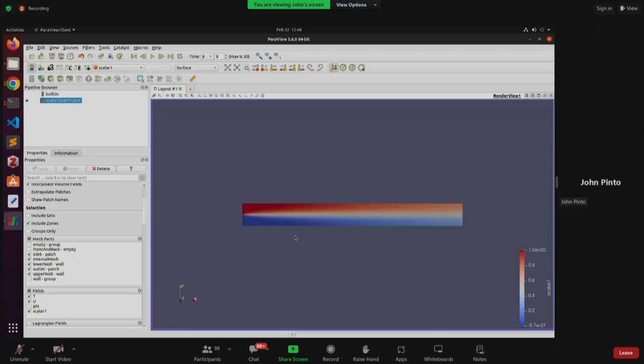So as sir was saying, in the micro reactors, the size is very small. So the diffusivity of liquids, even if it is not large, because the size is small, it diffuses. And this diffusion is what causes mixing. So here we are replicating that by using high diffusion, even though our sizes are not as small as those micro channels. But we are simulating, or seeing what results we obtain by increasing the diffusion.